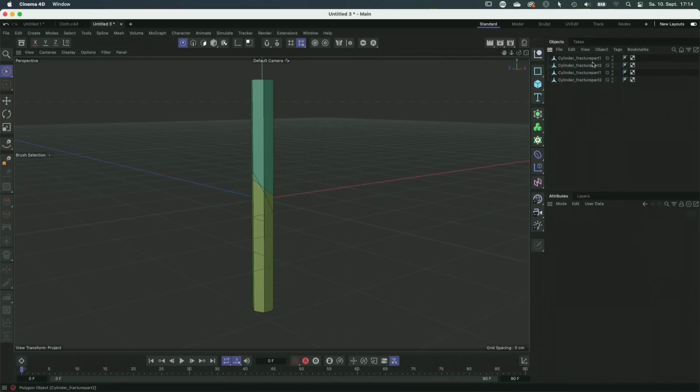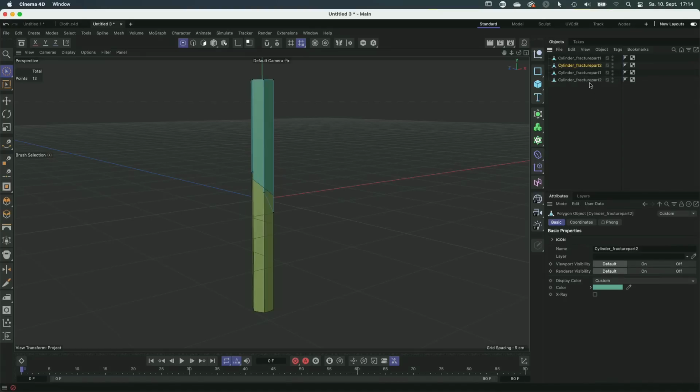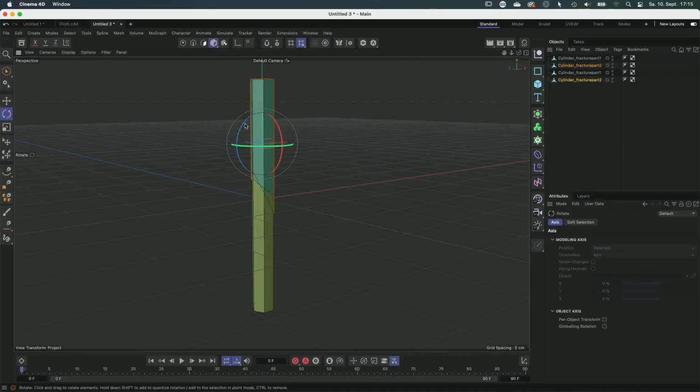These are our objects. So the first thing I'm going to do now is select these 2 objects, and I want to align the axes first. The axes always have to be at the bottom of the crystal, and they should be centered and aligned so that Y is pointing up. And the way I can do that is simply by rotating these, right?